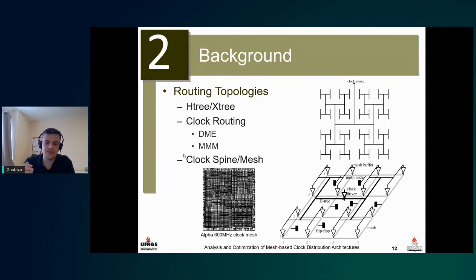So besides clock trees, we can also use clock spines and clock meshes. Clock meshes are basically a mesh of wires that we connect to the sinks of a clock tree. That mesh of wire provides us with redundant paths and actually short circuit paths between the outputs of all those clock buffers, which has a tendency of averaging out the delays at the sinks of the clock tree.